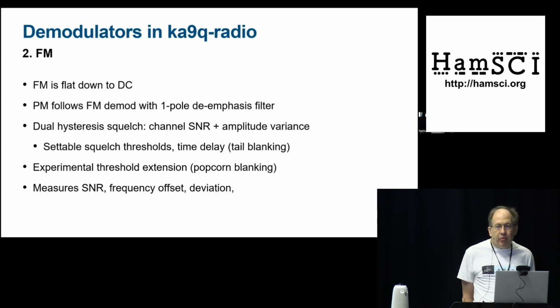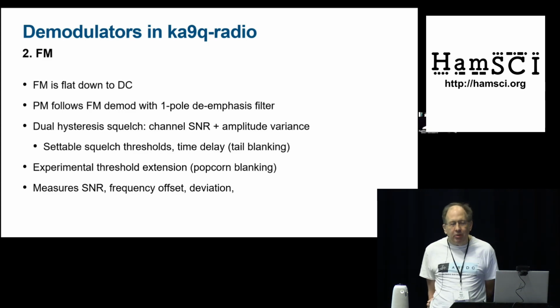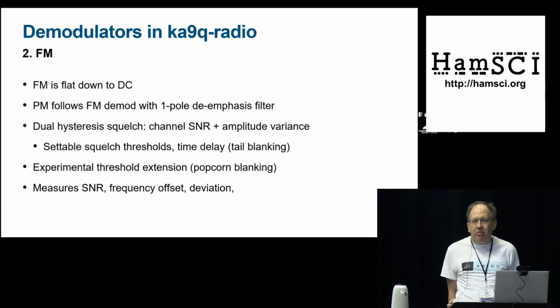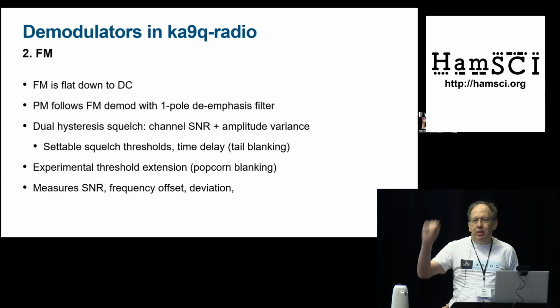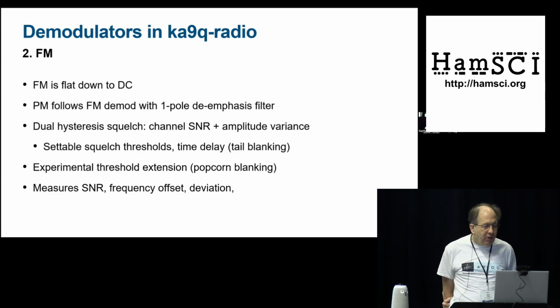And I've been playing around with the threshold extension. This is a concept that goes back to like the Apollo days. NASA actually had a lot of papers on how to extend FM thresholds because they were using it for video from the moon, and they were right at the hairy edge, and they were trying to get rid of the sparklies in the video. So I've been playing around with that. You get maybe a couple extra dB, right at the threshold of FM, and you start getting that popcorn noise.